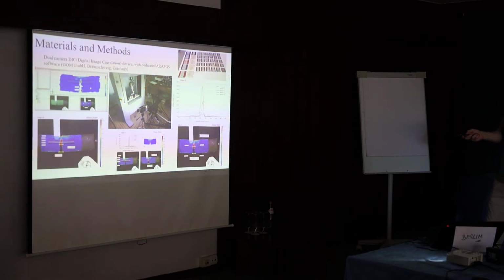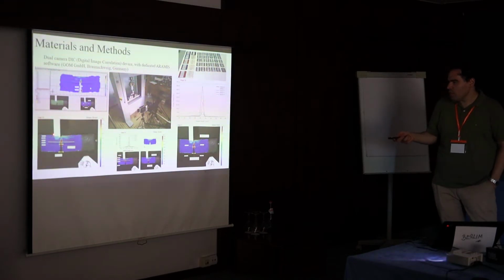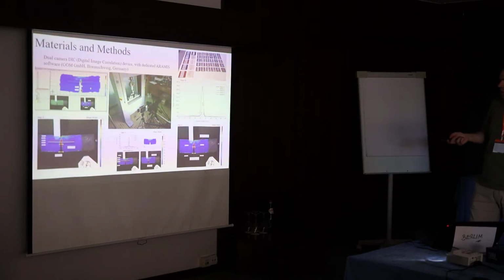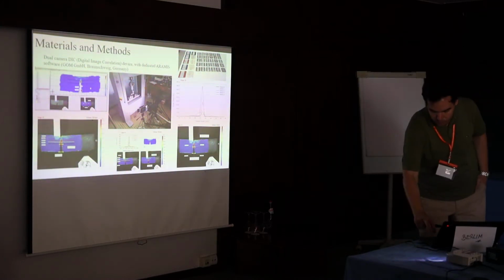It measures strain relative to the created sections. On the ligament of each specimen, we created 5 sections, like virtual strain gauges, where we monitored the deformation on the ligament side of the specimen.